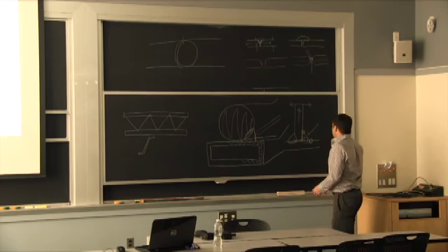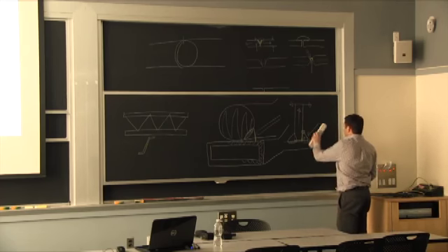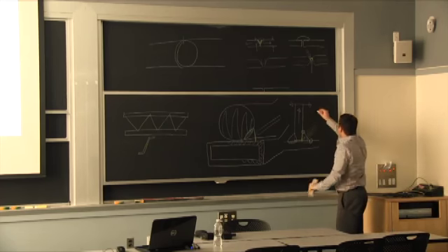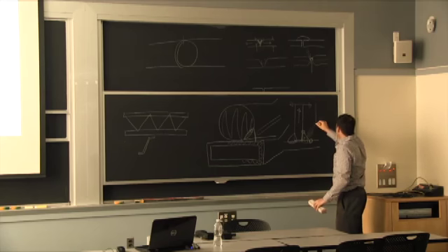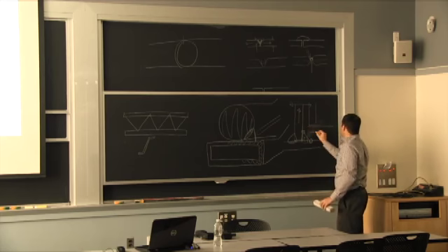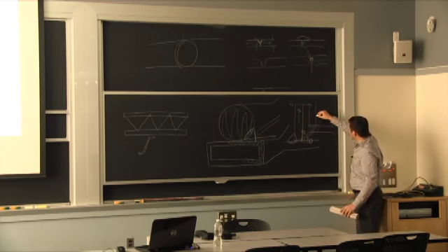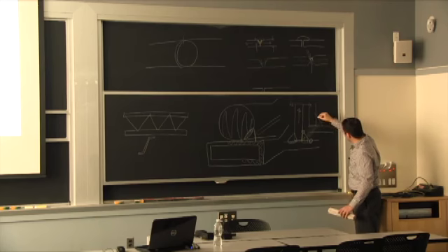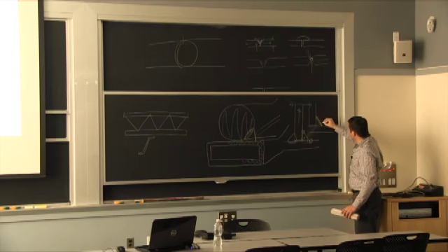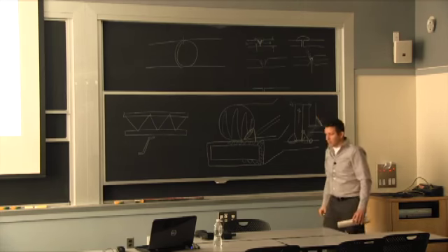So when I say good fusion, what I mean is I'm going to do another T. Good fusion has essentially a bead that has some convexity in most cases. Sometimes it can be concave, so I'm going to put it also as this. But you don't want to have it as a corner bead like the plastic ones.